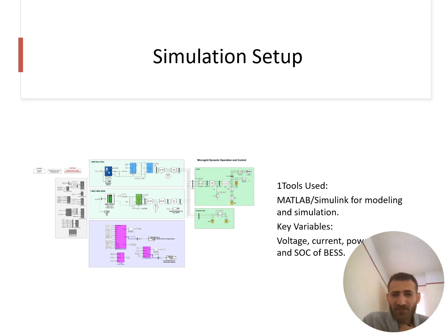Furthermore, our system incorporates strategies for maintaining a stable and synchronized connection between the microgrid and the main grid. This includes resynchronization units that manage phase, frequency, and voltage alignment before connecting to the main grid. By implementing these strategies, we ensure that the microgrid operates reliably and integrates with the main grid, enhancing overall stability and resilience.